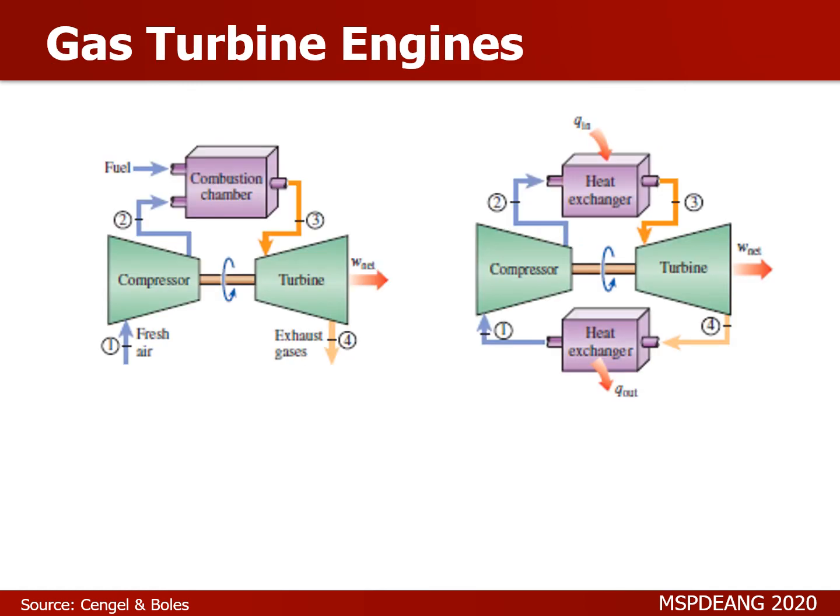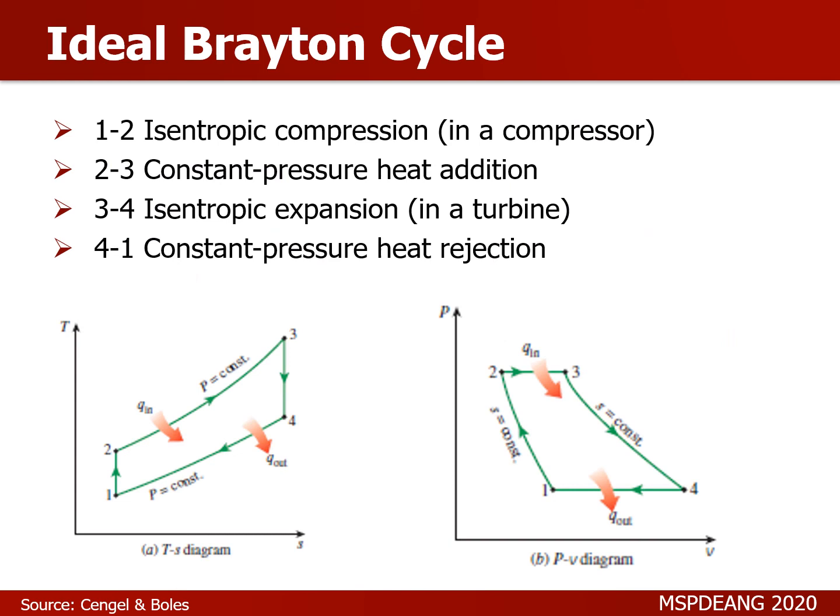Okay, and last but not least, you also have open systems gas turbine engines. So you can also use combustion and use these combustion gases directly in a gas turbine to produce work instead of using steam as your working fluid. Your gas turbine engines are most commonly known as your Brayton cycle. So for your ideal Brayton cycle, you have two isentropic steps and two isobaric steps.